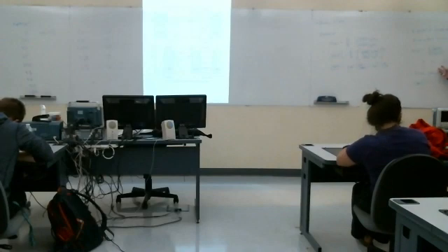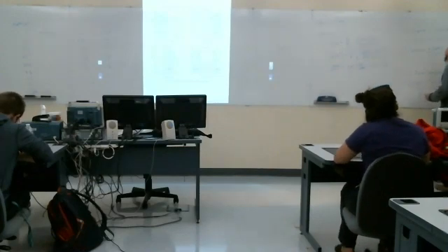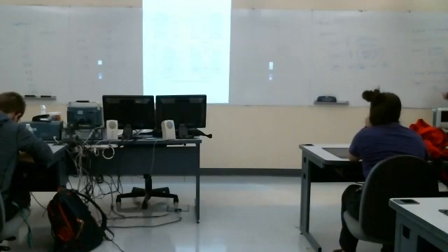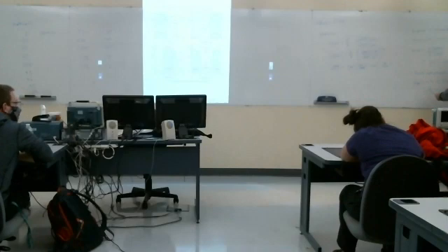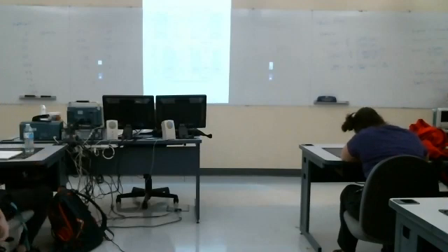So I'm viewing this as 10 times this divided by this. So this becomes 20 log of the absolute value of 10, which is 10, plus 20 log of the absolute value of 1 plus j omega over 8,000, minus 20 log of 1 plus j omega over 1,000.